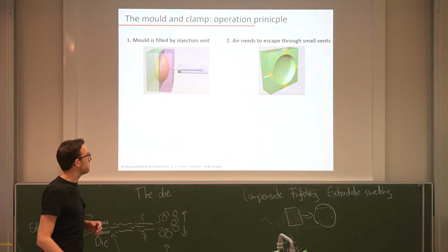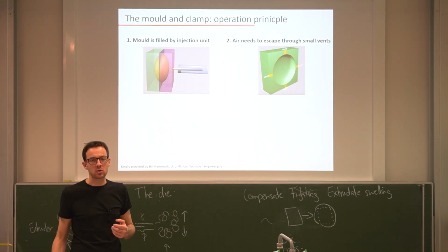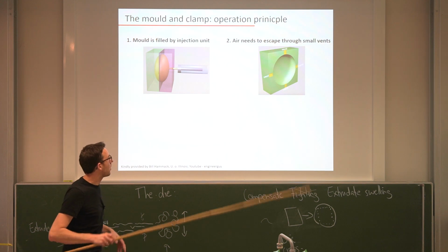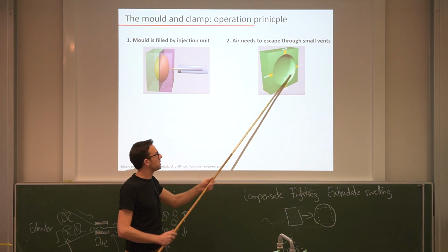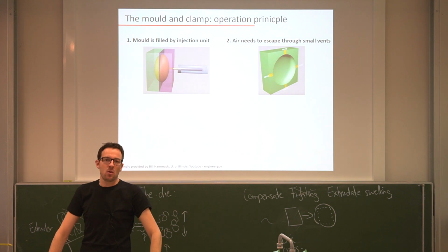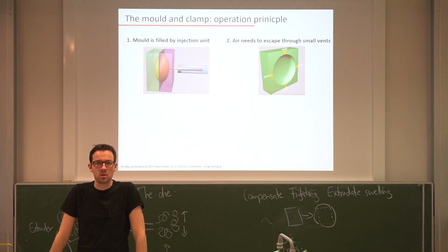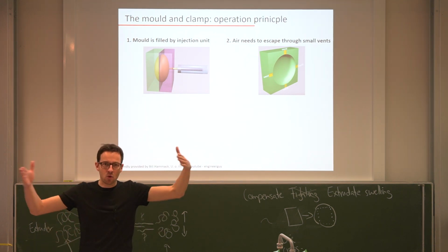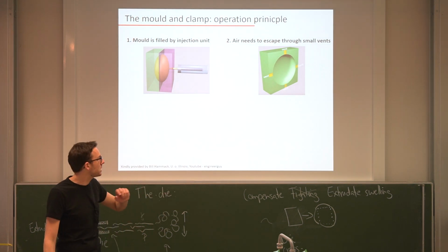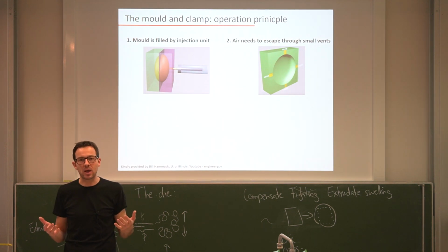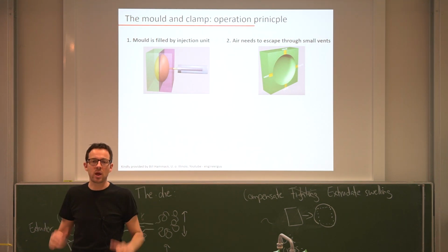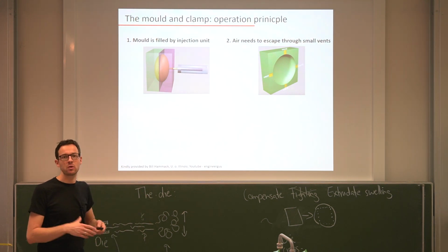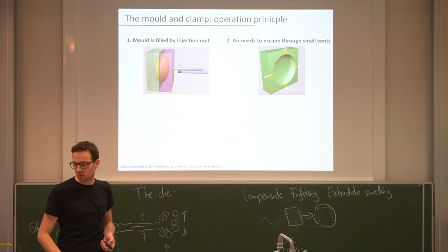Well, very simple. We need to drill in small holes, so that the air can escape. So our form has these small ventilation holes. So the next question is, why does the polymer not escape? Well, here again, this is an engineering problem. You need to make sure that air with an extremely low viscosity can go through these little pores or these little openings, but the polymer with a very much higher viscosity cannot. So you simply need to play around with the injection pressure and the size of the holes. And then you take advantage of the different, if you want, flowability of the two materials.